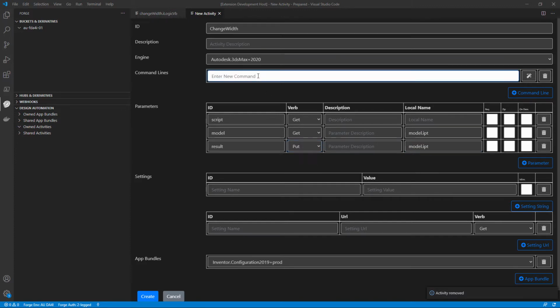On the command line, we ask to run Inventor Core Console exe sitting in path defined by engine variable. Using iSwitch, we define what model we would like to open. And there we have to specify full path. If we would specify only model IPT based on our local name, Inventor wouldn't open the model because he can open model only based on the full path to the model. Full path to your input model is specified by args dictionary with name of input parameter in key. In our case, it is model.